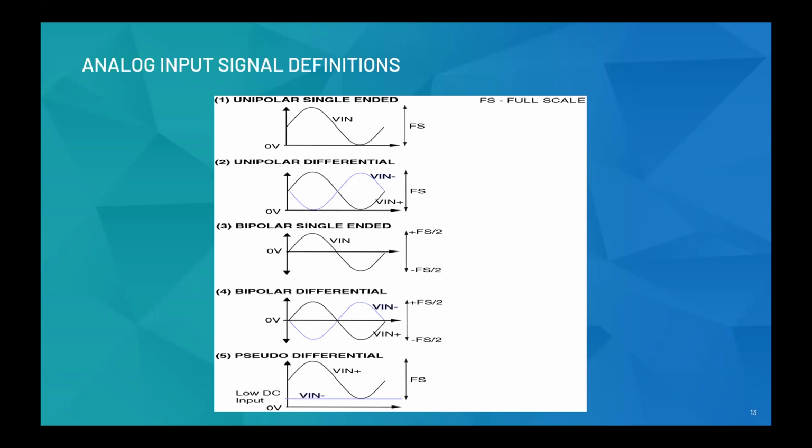And lastly, the bipolar fully differential, right? And the pseudo differential, wherein the negative end or the other end could be at a fixed value, any fixed value above 0, right? So that is called a pseudo differential input.